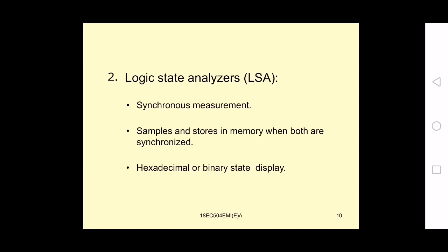So in case of LSAs, the display is either hexadecimal or binary state display. The logic state analyzer, compared to logic timing analyzers, is used for synchronous measurements, that is, samples are stored in memory when both the clocks are synchronized, and the display is either hexadecimal or binary state display.